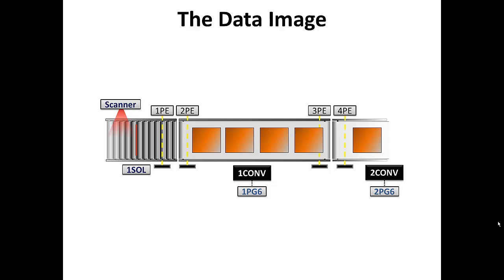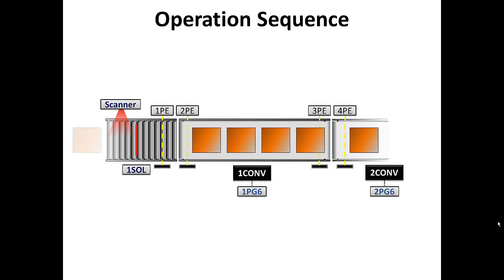Let's do that one more time. Only this time the takeaway conveyor may want the carton right away. So the carton comes in, stop goes down, takeaway's calling for one, so it turns on and it takes them completely away. So this is the basic idea, or the sequence of operation for our conveyor that we're going to use in our lecture on using RSLogix5000 to create multiple programs.